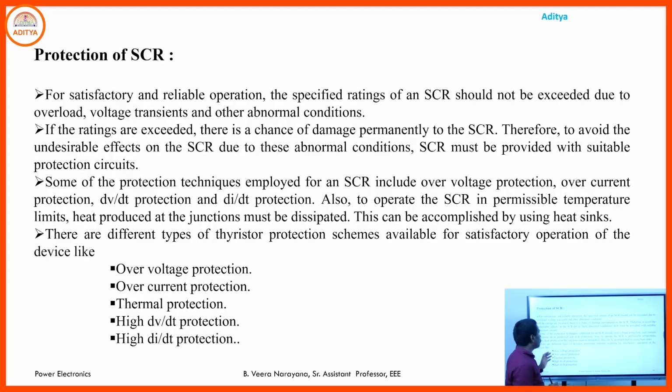But depending upon the switching condition of the SCR during the transient state, there may be a chance of the current flow through the SCR, or due to some abnormal operating conditions, the voltage across the SCR may exceed its rated value, hence why you need to protect the SCR.